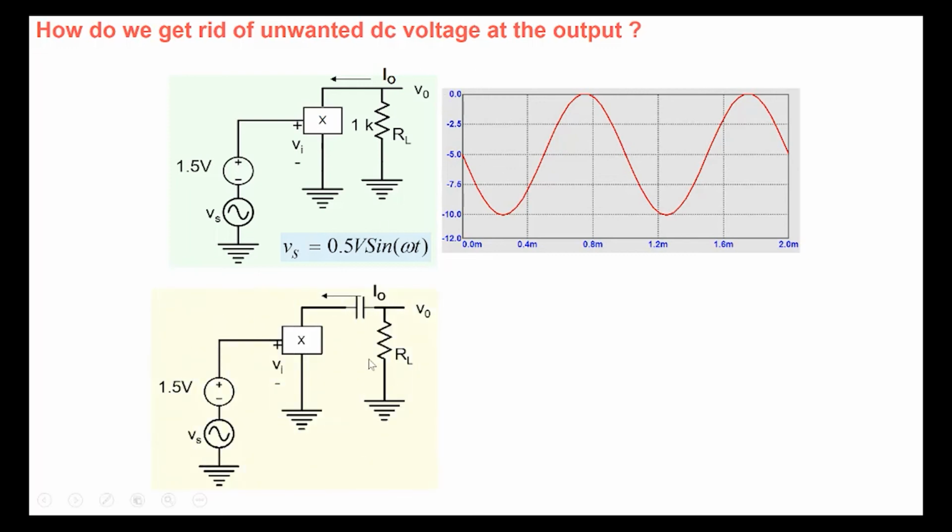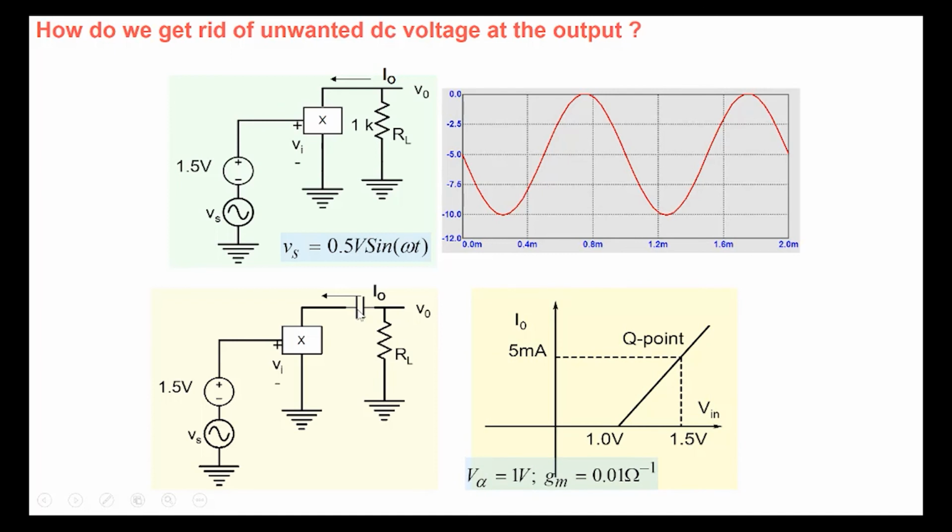So a simple thing we may think, well, let's put a capacitor. We don't want a DC current to flow through my load, and we want only the AC part here. So let's put a capacitor here. The capacitor is going to block the DC part here. But note the moment I put a capacitor here, well, the capacitor...